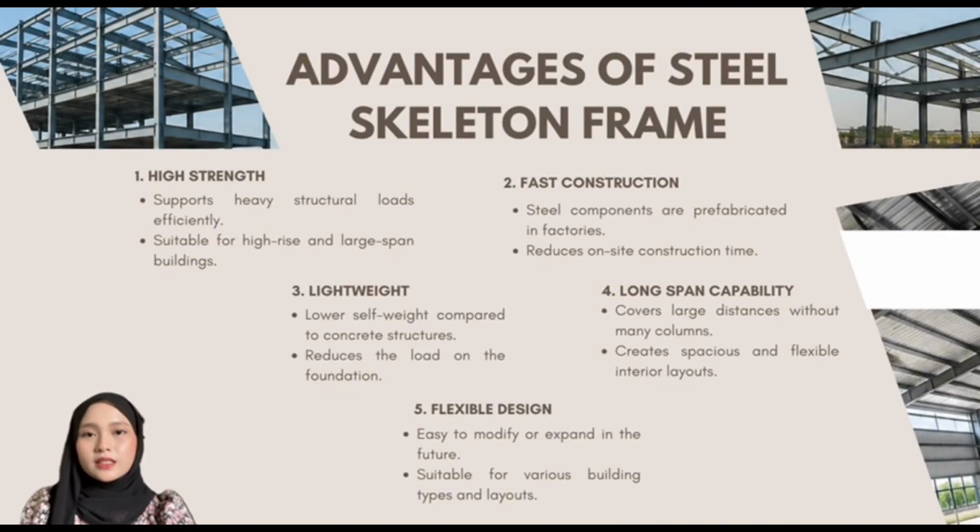Another advantage is that steel is relatively lightweight compared to reinforced concrete. Although it is lighter, steel still provides excellent structural strength. The lower self-weight reduces the load transferred to the foundation, which can also help reduce foundation size and construction costs.